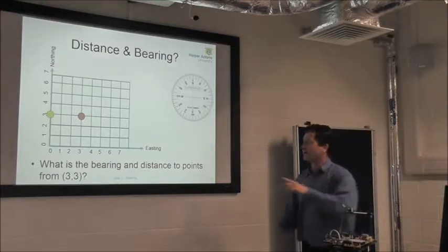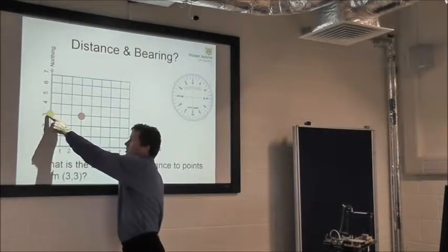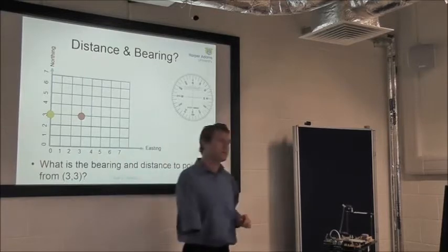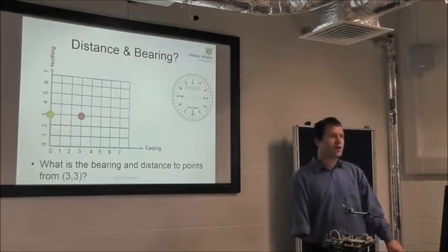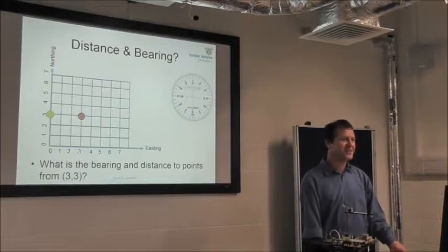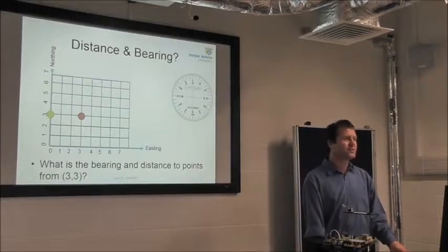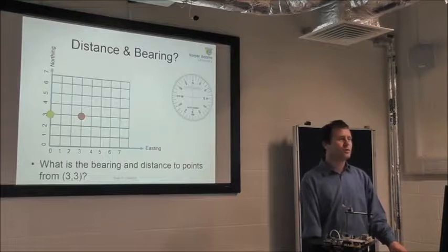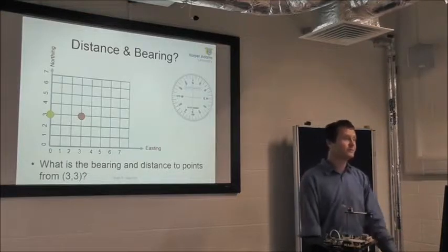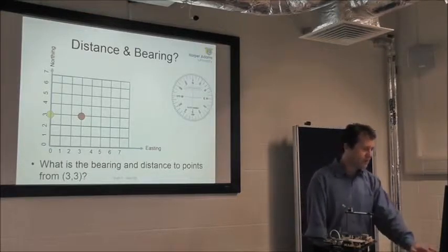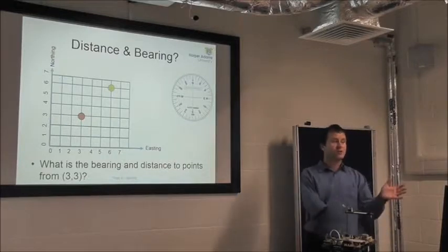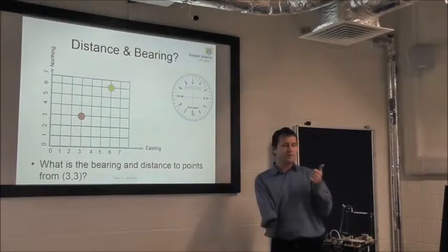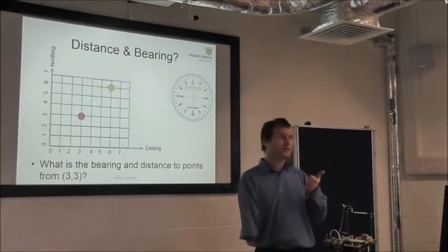So your goal, this will be the robot, and this will be our goal point, and we need to calculate the bearing to that point. Now, you've probably all done trigonometry, right? And you've used tan. So inverse tan will give you bearing, okay? So that's one way of calculating it. I've actually written a function that uses the tan function. In computers we use something called atan2.